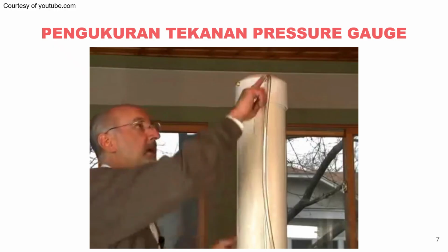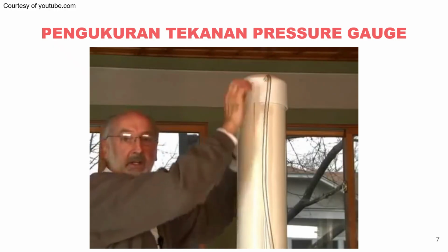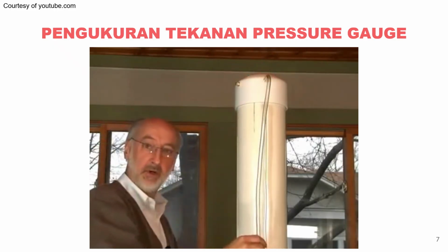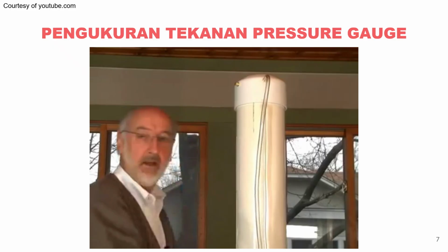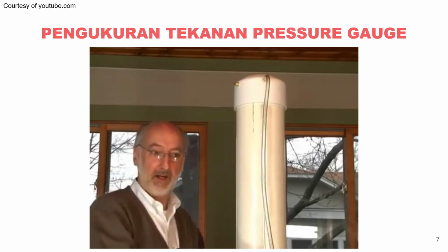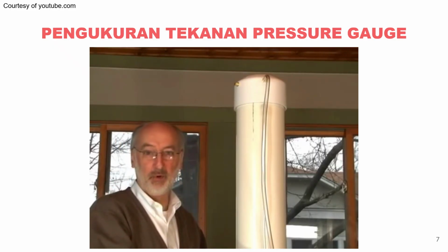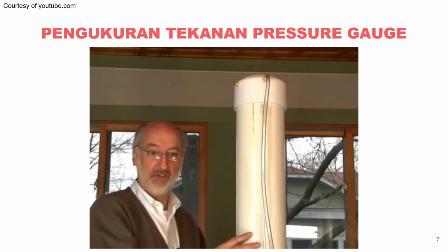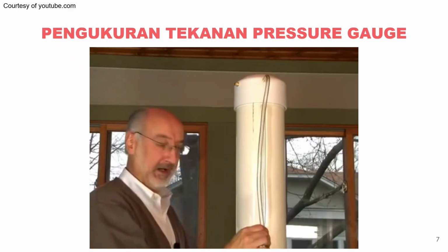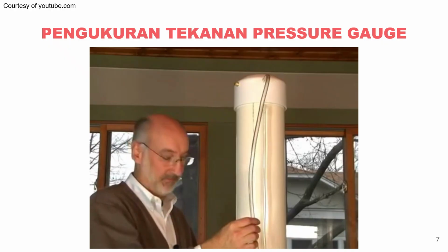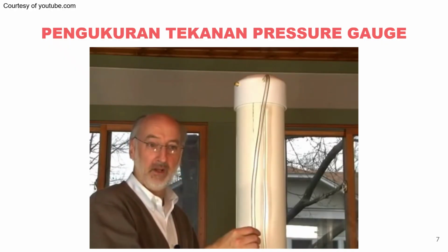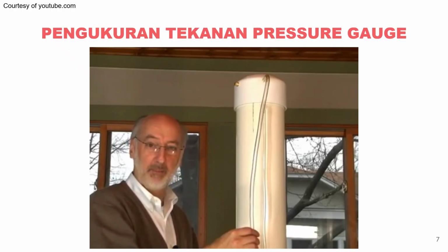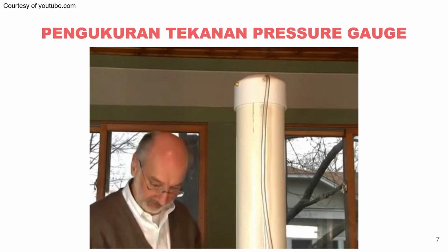Okay, now what I've done is I've put the cap on the tank, and I've connected a line to a compressed air tank. Now, bear in mind that PVC is not suitable for using compressed air. It's just not the right material for that, and neither is clear polyethylene tubing. So we're just going to gas this up just a little bit, just enough to confuse the pressure sensor.